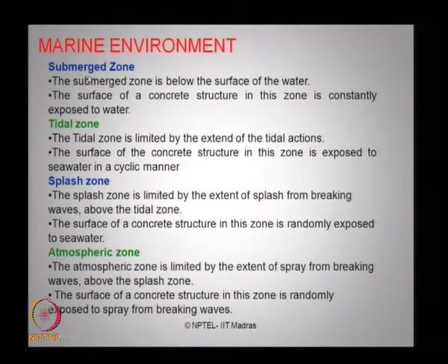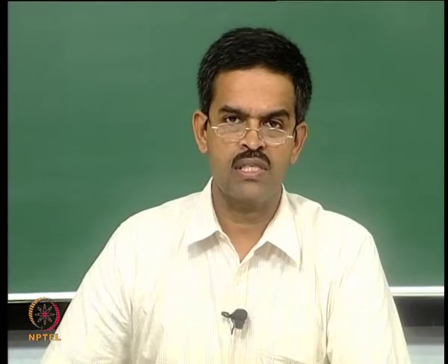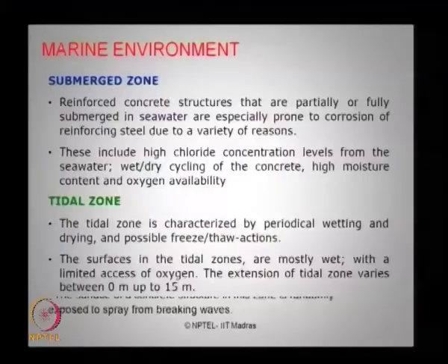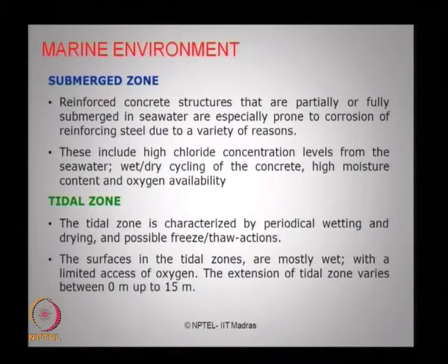However, the corrosion in the submerged zone is further lesser because of depletion of oxygen in this segment. If you attend to the submerged zone in detail, reinforced concrete structures which are fully submerged in seawater are especially prone to corrosion of reinforcing steel due to a variety of reasons. This includes high chloride concentration present in deep waters, wet and dry cycling of concrete, high moisture content and oxygen availability. There are many factors which contribute to corrosion even in submerged zones where concrete is either partially or